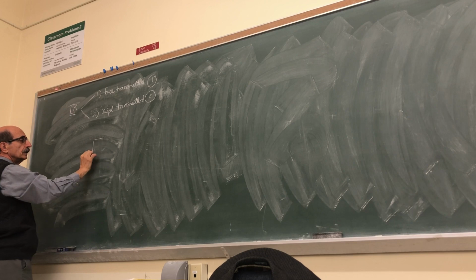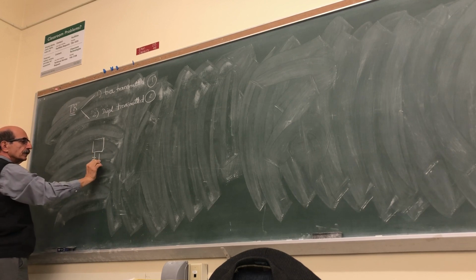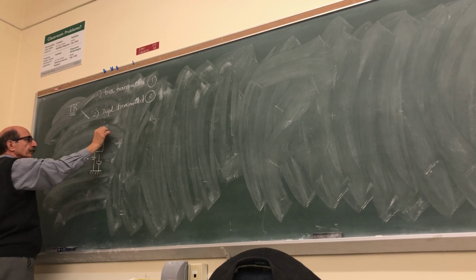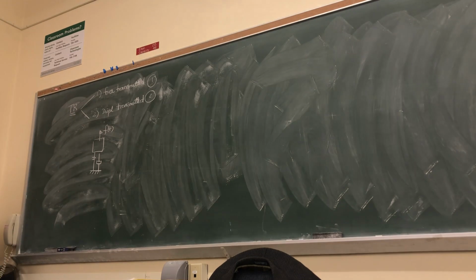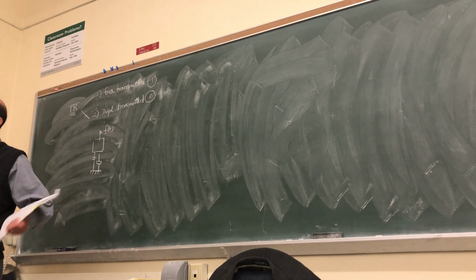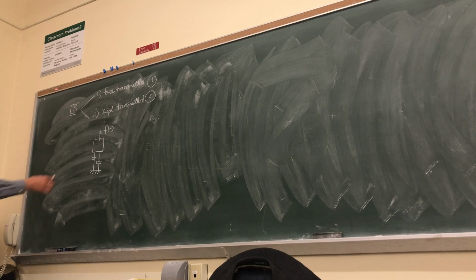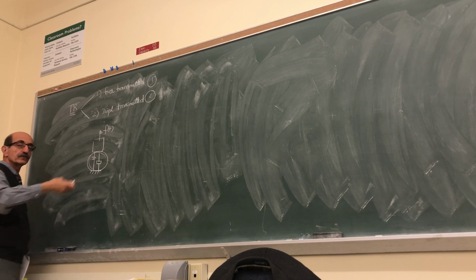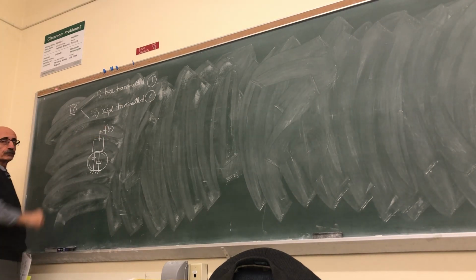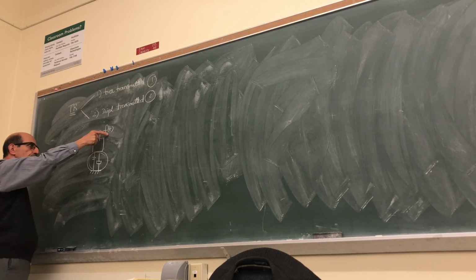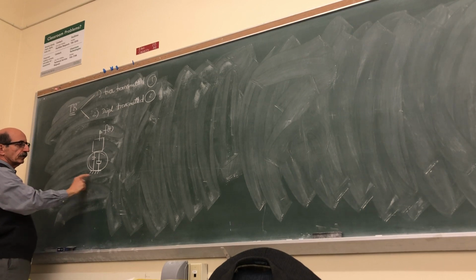So in case one, we had basically a system that is acted upon by a force, and we want to reduce the impact of this forcing function. For the time being, of course, we are assuming that it's a harmonic forcing function. We want to reduce the effect of that on this foundation or on the system, right, that is supporting this force. This force can be a rotating machinery force. We want to reduce the effect or the adverse impact of this on the foundation.